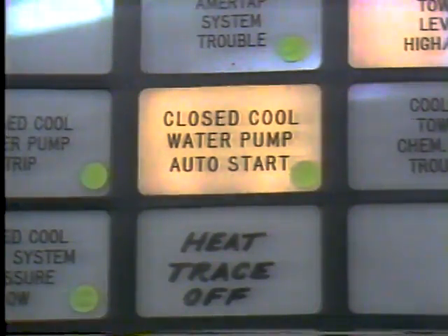Set point in the system is 85 degrees. When the technician changed set point to create load changes, the cooling water temperature did not vary more than 10 to 20 degrees above or below set point. As a safety feature, an alarm sounds in the control room whenever the cooling water temperature reaches 115 degrees.